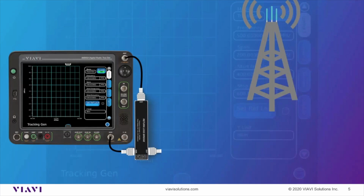Now, today, most of our modern transmitters have VSWR protection. They have circuitry that monitors the VSWR, and they will reduce their power or shut the transmitter down completely. And those are two things that you really don't want to happen at your base station. So we're going to show you how to test for that.